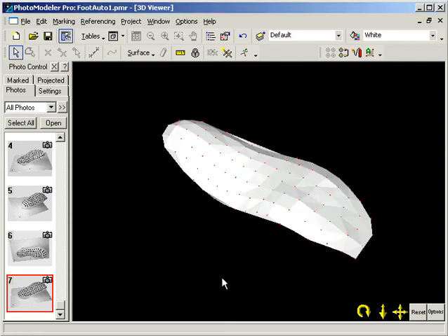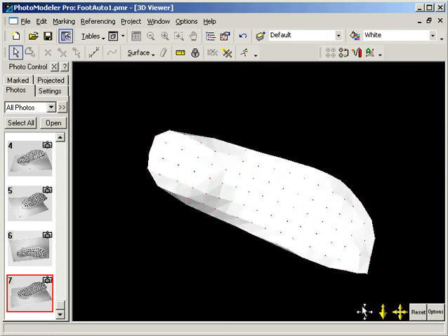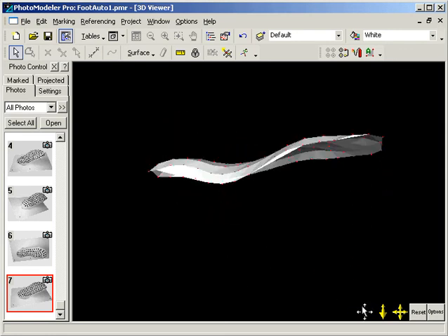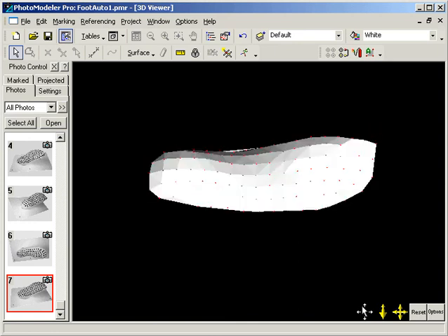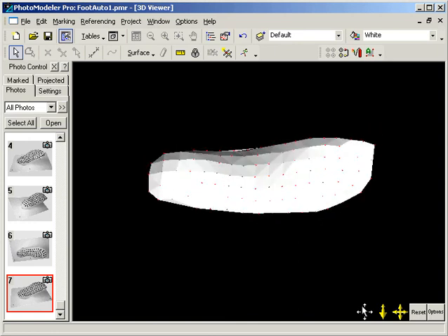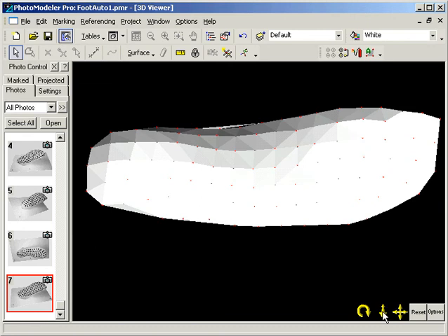We review the model in the 3D viewer. We can see that the surfaces have been created on the model. Overall, the surfaces appear to have calculated well. As we take a closer look, we notice this one surface back here does not look quite right. Occasionally, you'll find with the automatic triangulator that you'll get an incorrect triangle from your perspective. We will just select that triangle and delete it. We study the surfaces for any other problems.